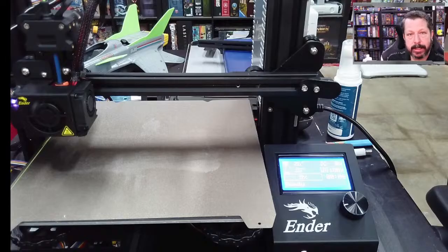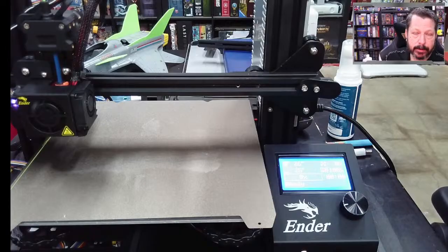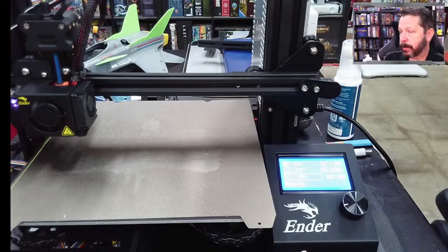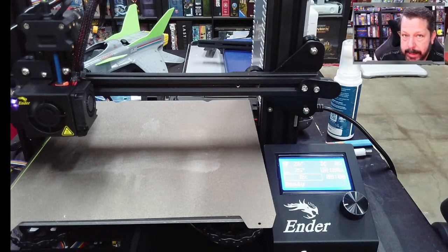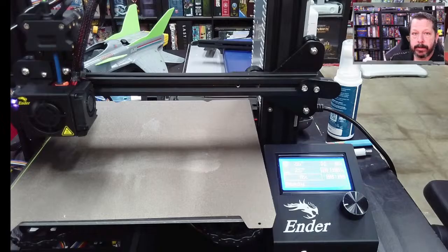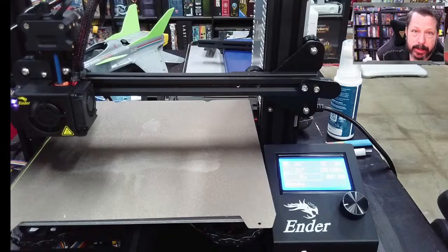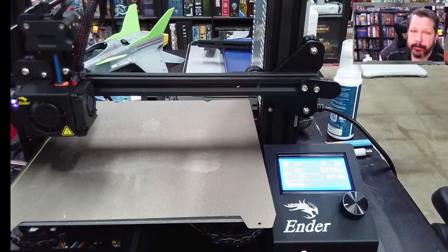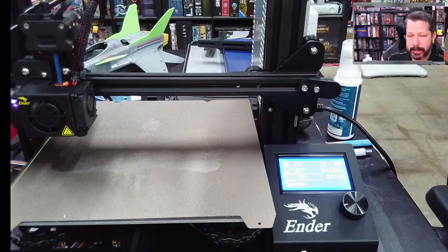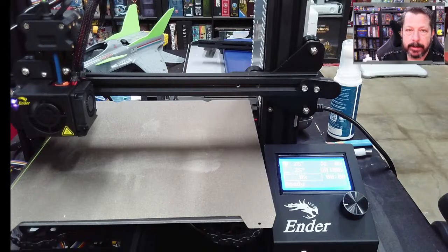Then that pressure that's in the tube will continue to extrude filament even if your feeder, the stepper motor, is not pushing filament out. So if you can tune that to where it retracts filament, it's going to pull the filament back out of the nozzle so that it won't ooze everywhere. So if you're getting really bad stringing, so you print your parts but there's little strings of filament all on it that you didn't plan to print, one obvious thing to check is your retraction settings.